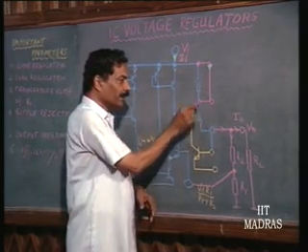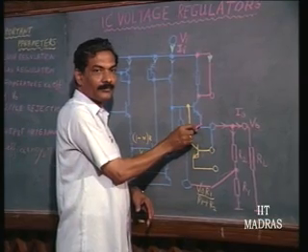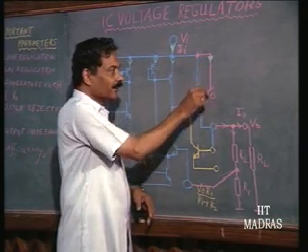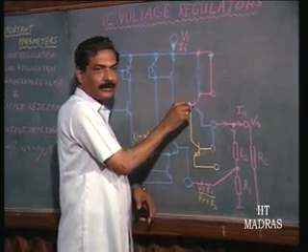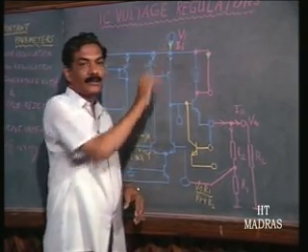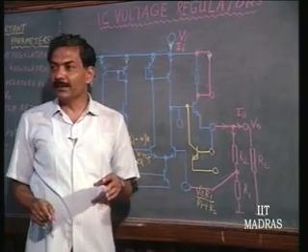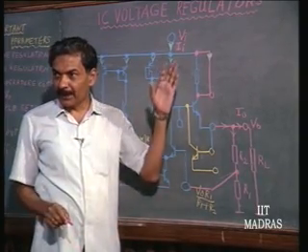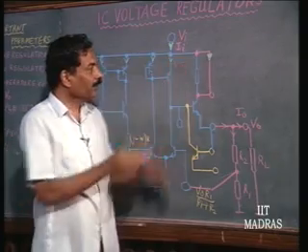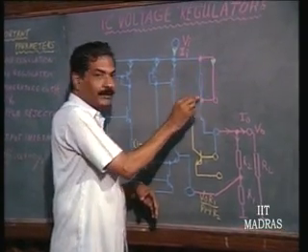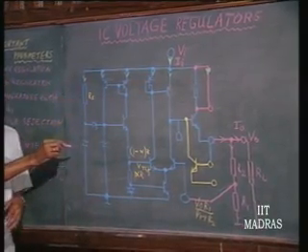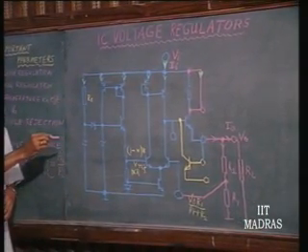If you assume that, then this current is going to be predominantly the output current. So, this output current is flowing through this, and it is essentially flowing through this, and that is going to be the dominant input current. Input current will comprise of this current plus the various bias currents of the IC.